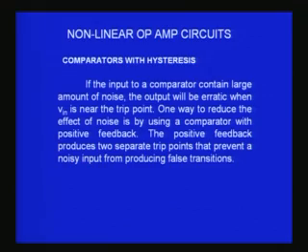This plus or minus 150 microvolt is what is called hysteresis, for a reason which I will explain in a moment. It would be better in many applications to have this difference, plus 150 minus 150, much larger than this small value. For example, plus or minus 1 volt or plus or minus 2 volts as the case may be.